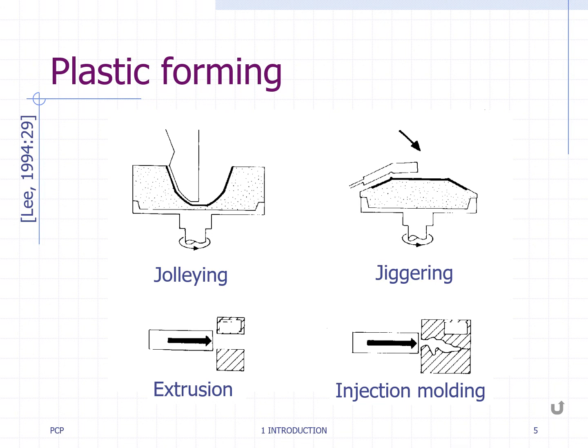In the case of injection molding, the feedstock is a mix of powder and additives, mainly binders and plasticizers, which are fed as granules. Differently from other ceramic shaping processes, injection molding is generally not carried out at room temperature. The system must be heated up to permit that a paste is formed and fills the gap, usually of a complex shape and small piece, which is produced at high speed and efficiency.